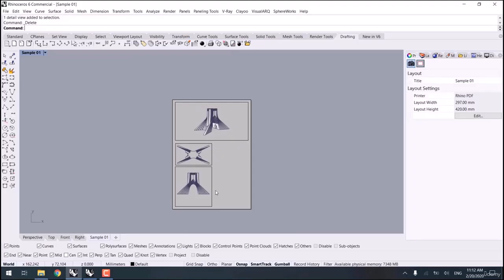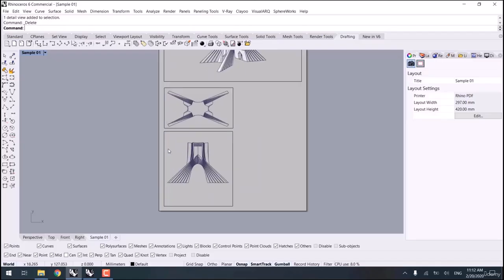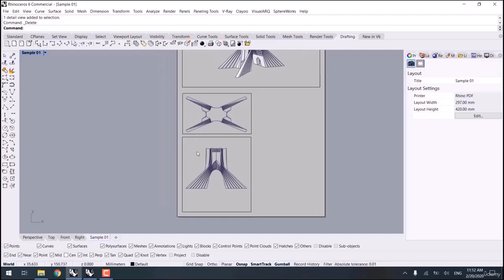So this was the way that you can create the layout and then adjust the detail views. And the advantage here is that you can specify the dimensions of each of the members or items. For example, the size of the page is A3 and the size of the detailed views are specified. But here you may ask that we haven't specified the scale factor.